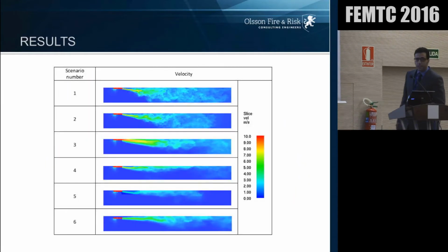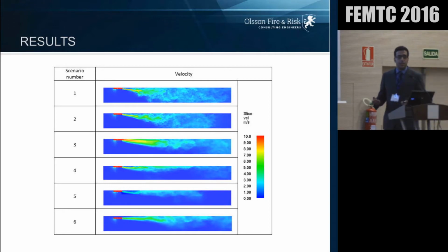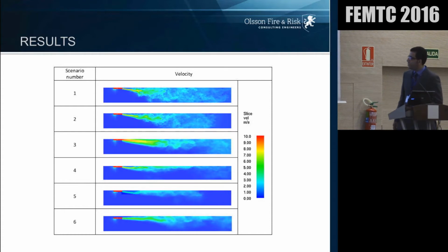So running through the results, the very fine mesh is what's represented in case number 1. And if you compare it with the rest of the results we have on here, maybe number 2 is quite comparable to number 1, but everything else on here is very different. Number 5, actually, I found to be the worst representation of the result, because simply we have the embedded mesh, and I think in FDS, the communication between 2 different overlapping meshes is not as mature as it should be.